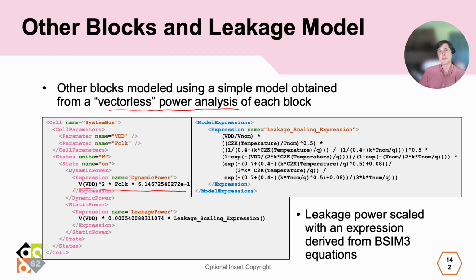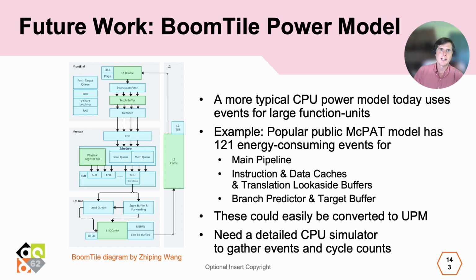If you look at the leakage power, you'll see that, again, it's a simple leakage power for each block. However, we do have this leakage scaling expression, which was derived by Jerry Frankel, who's on the IEEE 2416 team, from the BSIM3 equations. And that just illustrates how you can use a complex expression to see how that leakage power will vary with temperature and voltage. So that sums up the power model that you'll see packaged with this tutorial.